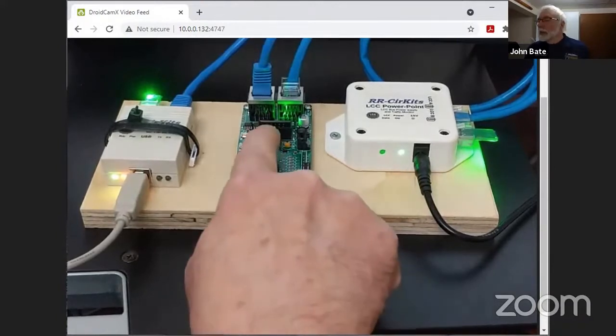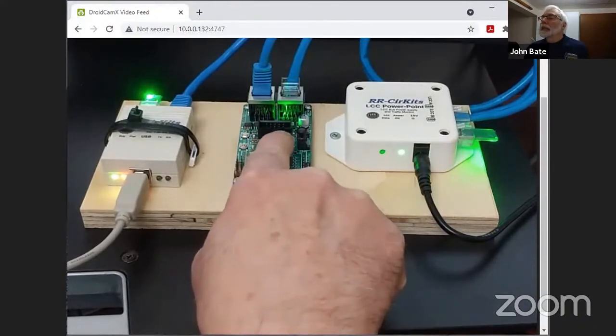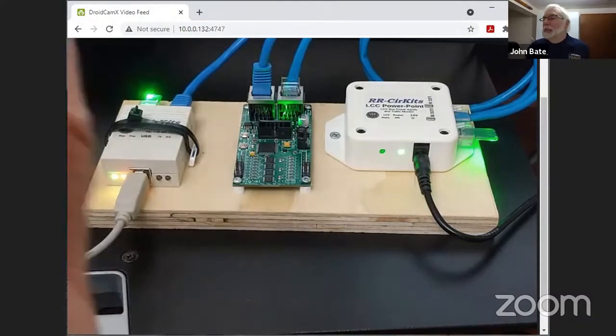And this little connector right there that I hopefully can point out, that contains 8 general purpose input-output pins. You can use them as inputs, outputs, whatever you want. They're digital logic, 5 volts, 0 volts sorts of outputs. You can get things that plug into them that control more complicated things like relays and servos and stuff like that, that requires a little bit of guts and a little bit of power. But they can control 8 things, 8 lines.